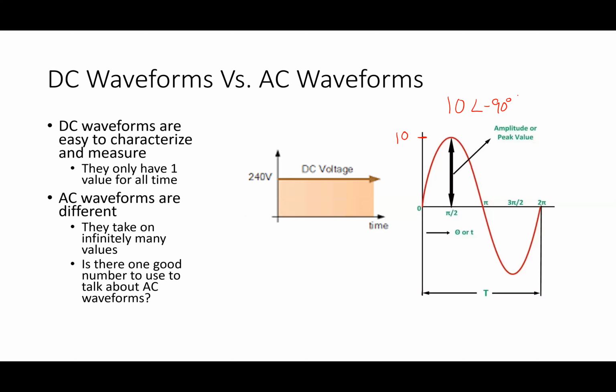We're going to see more about that as we go through this, but I want to first introduce this concept of RMS because, quite honestly, if you go and talk to an engineer at Duke and they say, "Well, this is 120 volts right here," they're referring to a sine wave, but not one that has 120 volt peak amplitude. They're referring to a waveform that has 169 volt amplitude, okay?